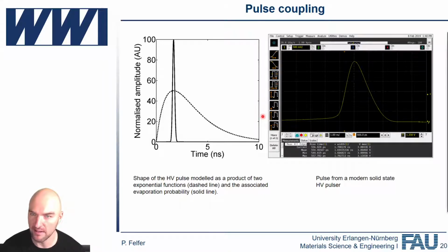In this case, the image that you see here is actually done with a proper high voltage attenuator, with a BEHLKE attenuator, with a very high bandwidth, by our colleagues in Russia that built the pulser. The downside of those attenuators is they can only do very low pulse repetition rates, and they're very expensive. So I've never bothered buying one because we can just put it in the end of the pulse line.